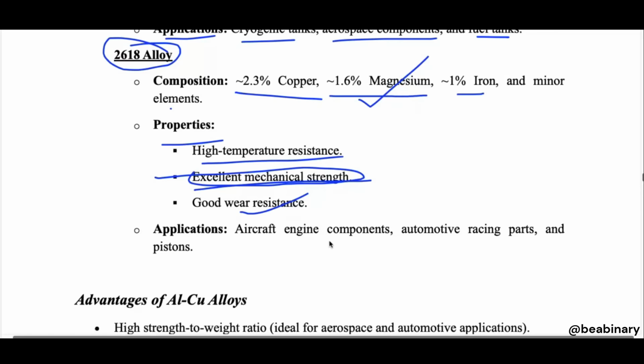The same thing happens in corrosion as well, but you must be clear that in corrosion you are also eroding the material from the surface. But in that case you do not have the rubbing nature. The two components are not rubbing or moving together. In corrosion, it is just due to the environmental effect. A chemical reaction happens on the surface, and it depends.